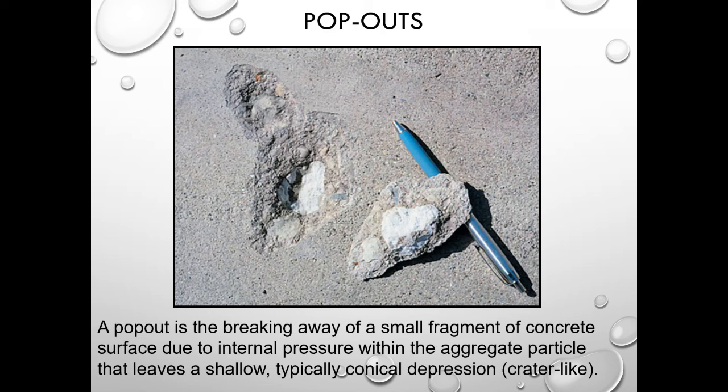If you look at this type of distress on a pavement, and this can actually happen on asphalt pavement also, can you imagine having this on a runway where you have jet engines? They would suck up this debris off the surface if this was occurring, and it can be catastrophic. Damage can occur to the engines, and even fatalities can occur. So this is one type of material to look for, and be very cognizant of the fact that it can cause some severe problems.